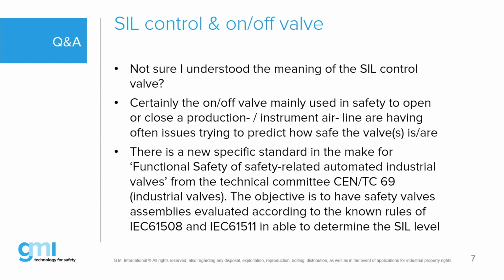So what they were selling to you mainly was a piece of paper for one specific device, which most likely was correct in what the statement was saying. But once you start to assemble the entire valve to carry out a safety function, that is typically where some of those certificates were misleading, with a misunderstanding of the functionality of the valve reaching a certain SIL level. Yes, Paolo, coming to the next.